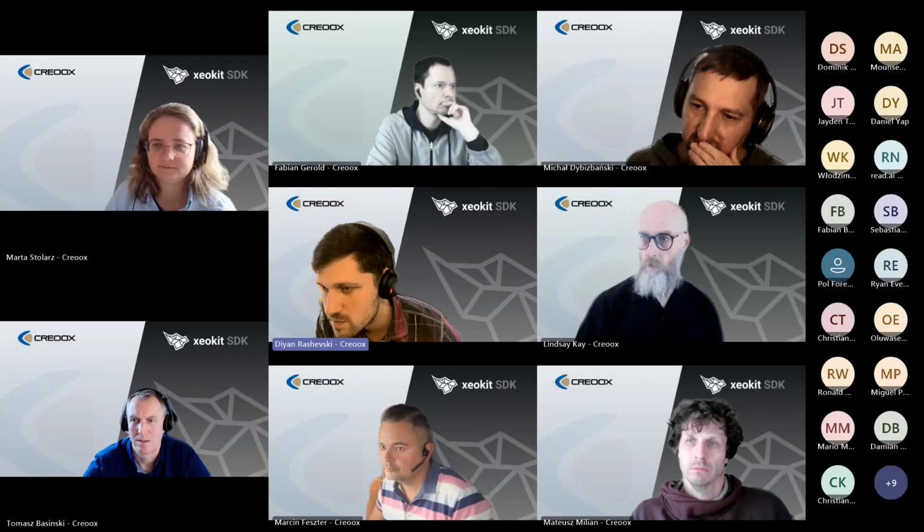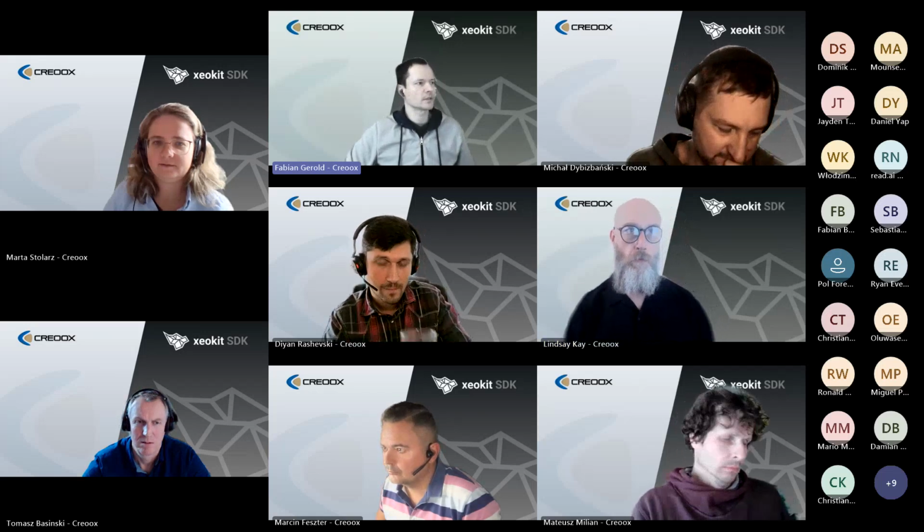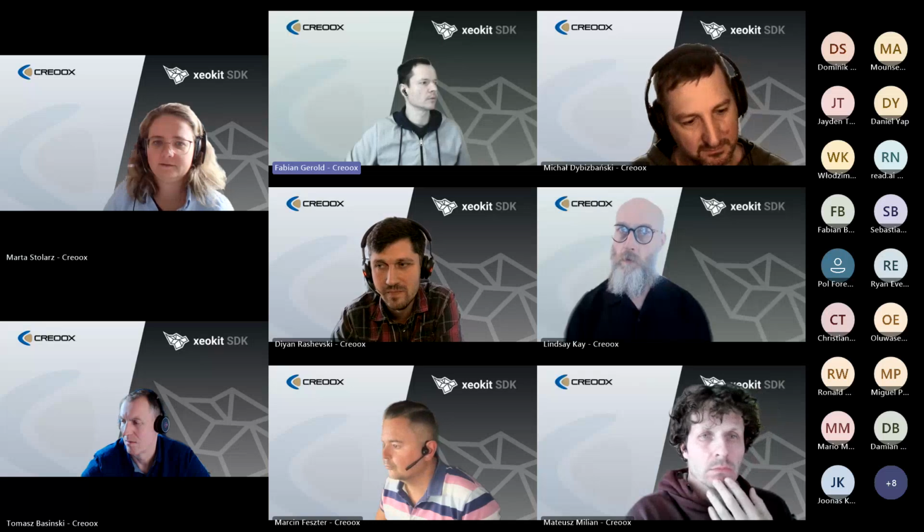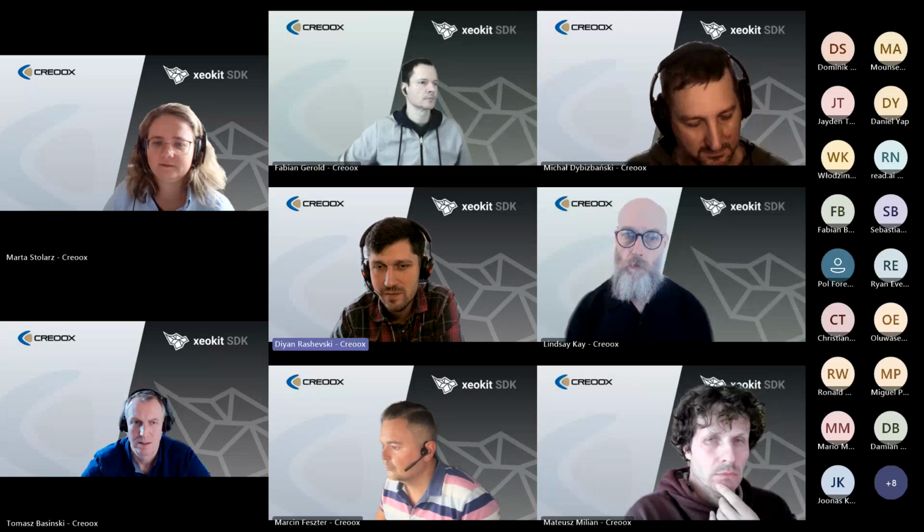And then, what is the maximum size limit for IFC for the cxConverter? Yeah, there's no limit, actually. The limit is your compute resources, RAM and disk size. But other than that, there's no limit. Our biggest test file that we have right now is a 2 GB IFC file from Baku Stadium. We saw it in Lindsay's screenshot, and it renders quite smoothly in xeokit. So 2 GB is not the limit at the moment. It works quite well.